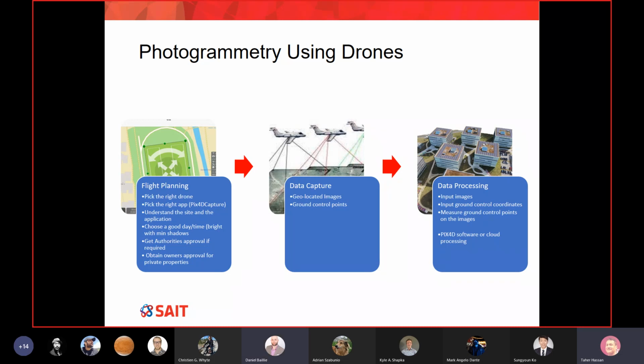You'll probably run into issues with the battery when it gets that cold. Exactly, sir. That's exactly it. So the manufacturer will tell you the safe operational range. For example, it will tell you between 0 and, for example, plus 35. Within this range, you should fly your drone. Otherwise, there could be a problem with the battery. And if a problem arises with the battery, you know what happens, huh? Your drone will fall to the ground.